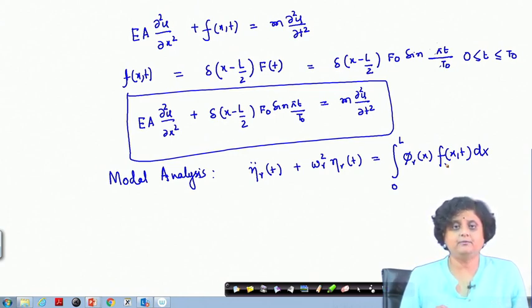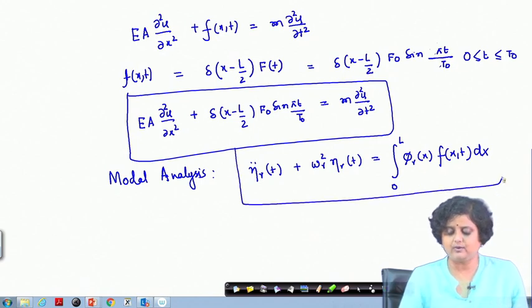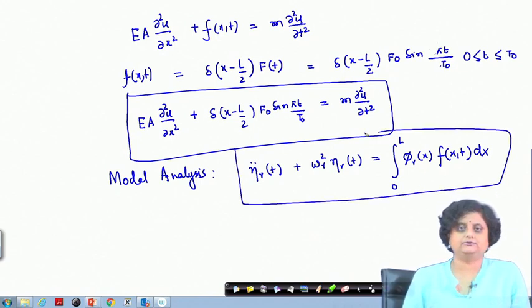We solved the problem, we derived this equation from a very generalized equation of motion of the system, which had no criteria of uniformity of cross section. So, whatever be the system, till the point it is linear, that is what we are dealing with in this course. It is a linear vibration course. Till the point it is linear, we do not have to bother. We know that whatever be the equation, this is going to be the equation after modal analysis.